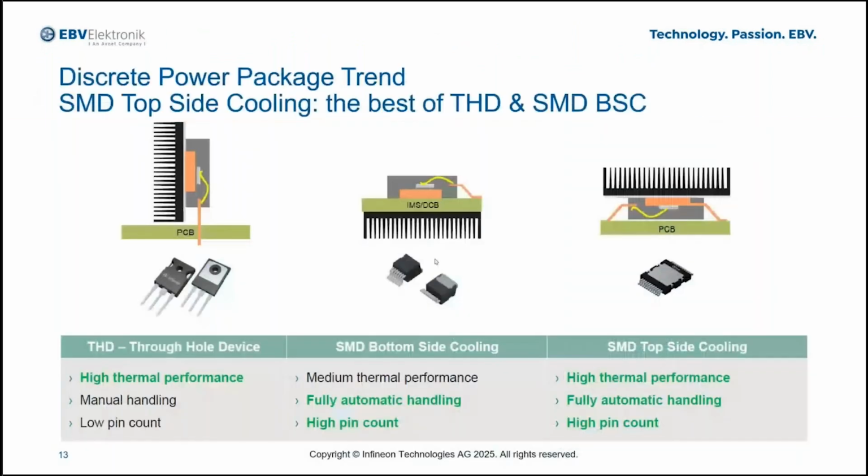So what is topside cooling? It's basically a power package trend, mainly on power discretes. The idea is to combine the advantages of through-hole devices and SMD devices. The advantage of through-hole devices, especially in TO-247, is the high thermal performance. But the drawback is that it requires manual handling and it has a low pin count. Therefore, package inductance is sometimes a limiting factor, whereas the die inside could switch much faster.